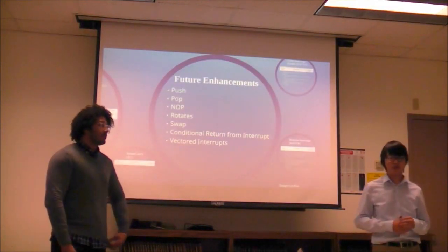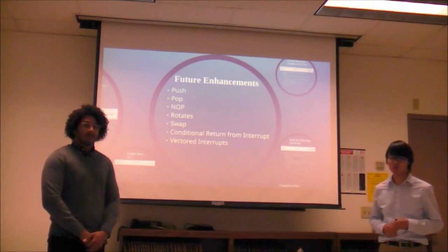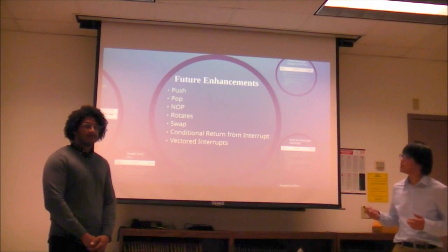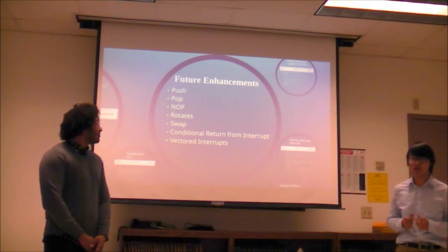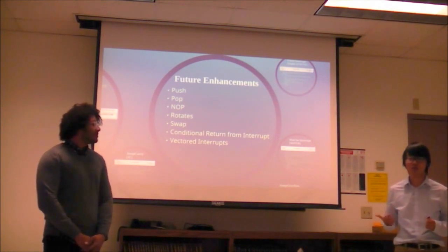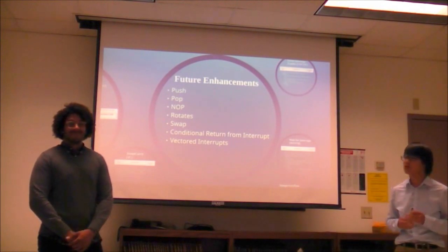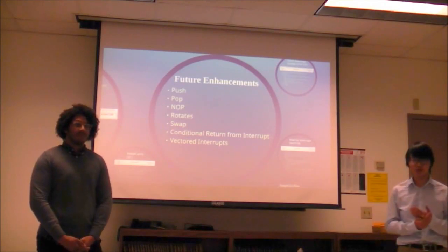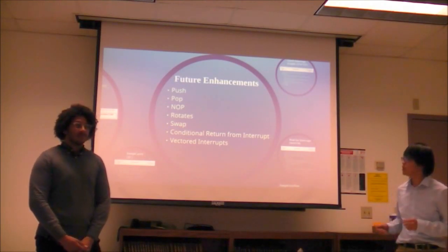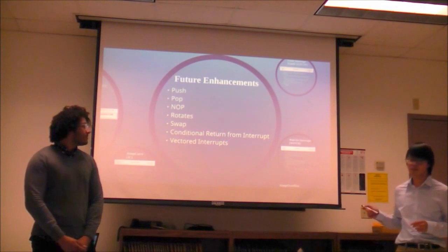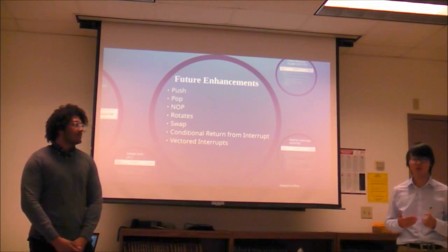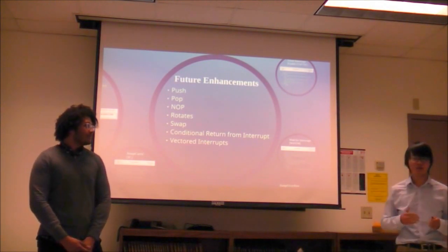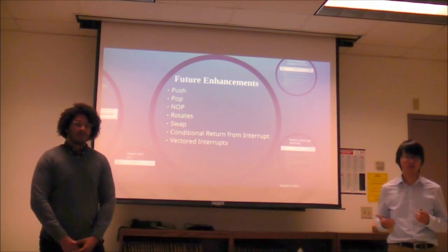So those are the enhancements, but due to lack of time, there are things we would want to further enhance in the future. These include push and pop instructions, a no op so the user can have a little wait, a rotate, a swap so we can swap the values of two registers, a conditional return from interrupt so we have more control over when we return, and a vector interrupt so we can have more than one different interrupt.